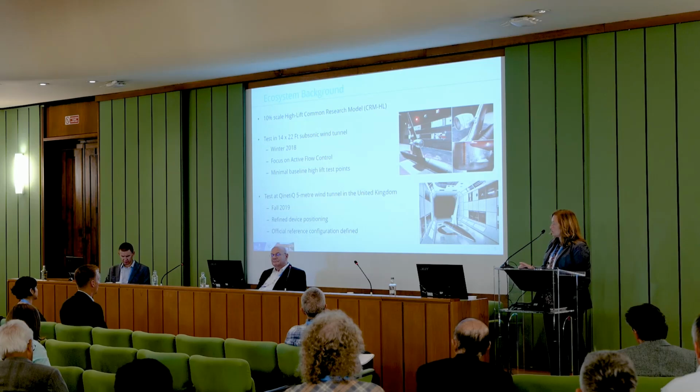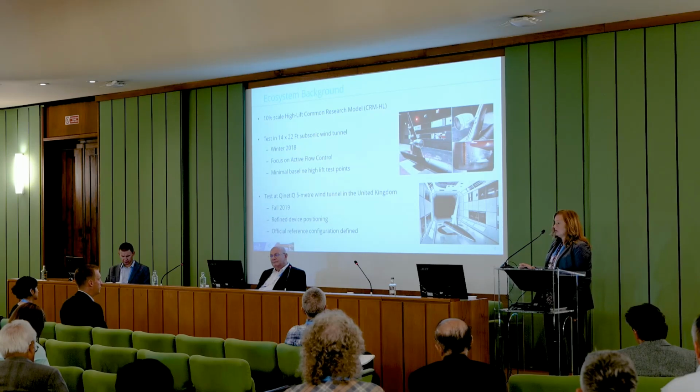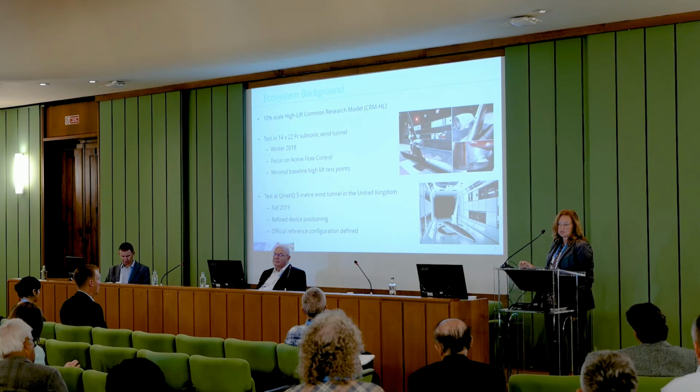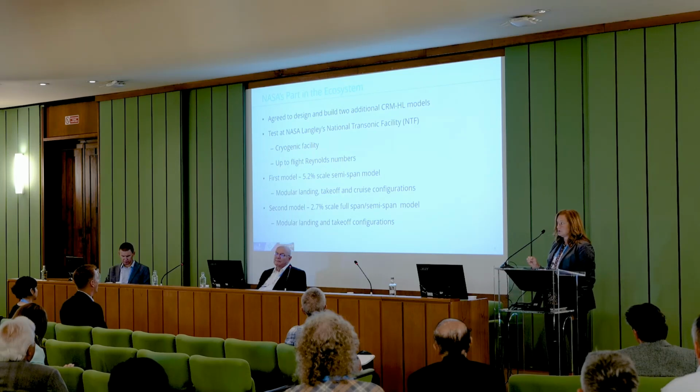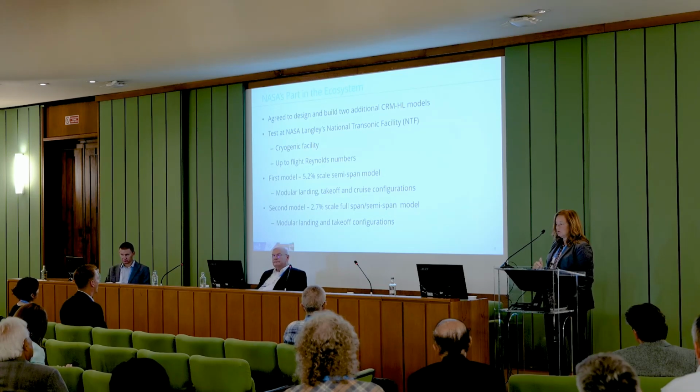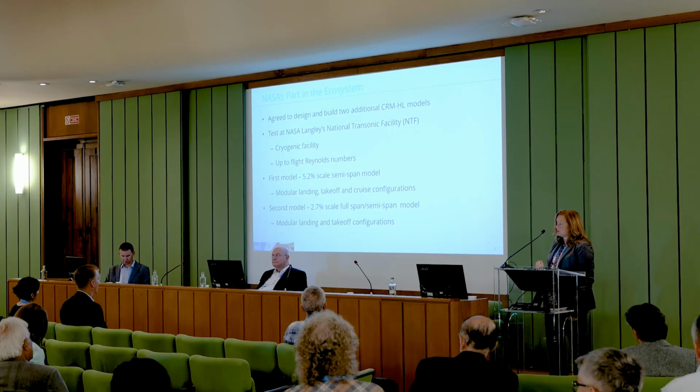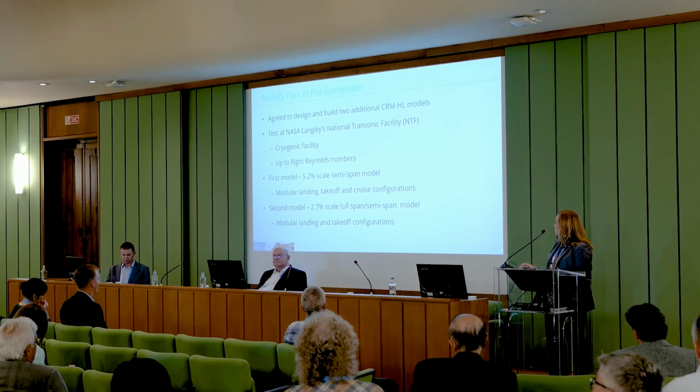A year later, we took the model to the Kinetic 5-meter tunnel in the UK. There, as was already mentioned, we refined the device positioning, and the official reference configuration was defined. From there, NASA agreed that we would build 2 additional CRM high-lift models. The focus of these would be to be tested in the National Transonic Facility, the cryogenic facility at NASA Langley, and we would test up to flight Reynolds numbers. So this would be something unique on these 2 models.